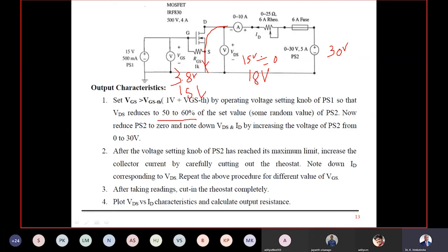So normally when you talk about the MOSFET or transistor, you take BJT transistors, it has got only two applications. First application, I can use transistor as a switch in all the digital circuits as well as in the power converter. Second application, I can use transistor as an amplifier, power amplifier, audio amplifier, video amplifier, or any amplifiers. So transistor purpose is only two. One is the amplifier, one is the switch. So when you go to saturation region or cutoff region, it will be permanently turned on or permanently turned off. When you maintain the transistor in the active region, it will be in the amplification mode.